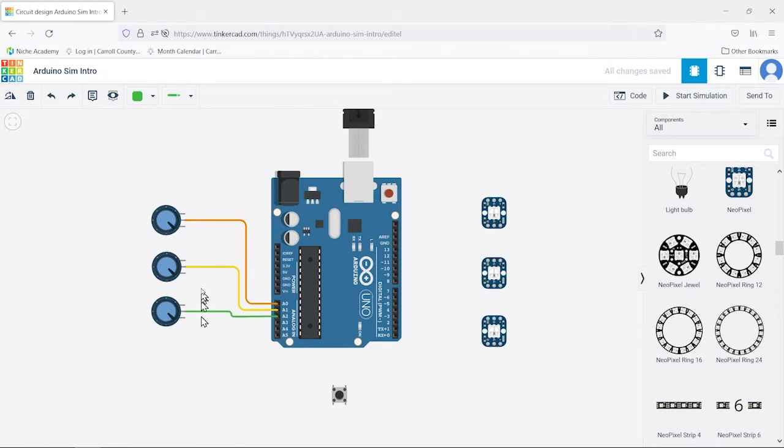The humble potentiometer can be found in almost any device with a level control that varies from 0 to 100%. So think of devices with a volume control, such as a pair of headphones, or a stereo system, or even a light dimmer. Before writing any code, let's place all of the components and get them connected. Potentiometers are 3-pin devices, with the outside pins being connected to positive and ground as signified by red and black wires. The middle pin is the signal pin, and will be connected to the analog input side of the Arduino.